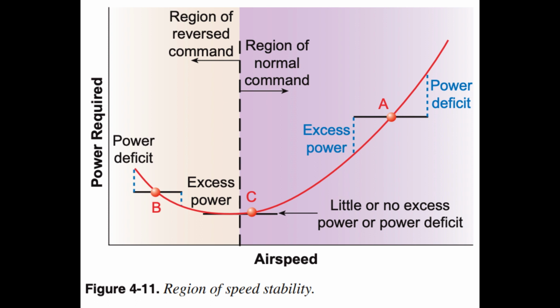If the airspeed is reduced with no changes to the power setting, an excess of power exists. The aircraft has a natural tendency to speed up to regain the balance between power and drag. Keeping the aircraft in proper trim enhances this natural tendency. The static longitudinal stability of the aircraft tends to return the aircraft to the original trimmed condition.